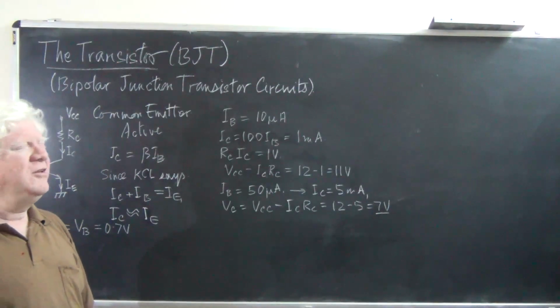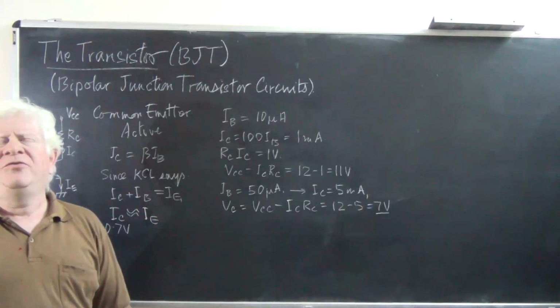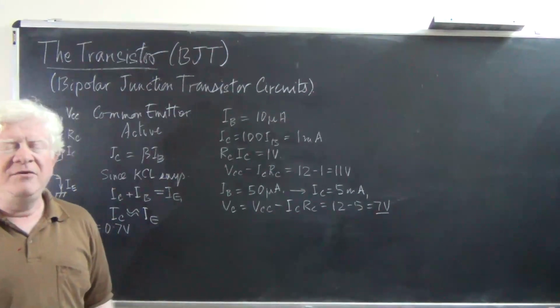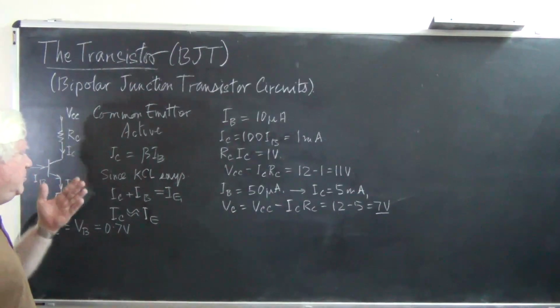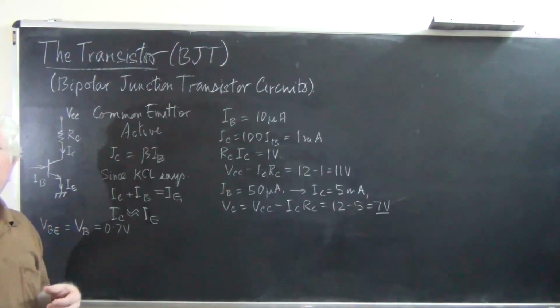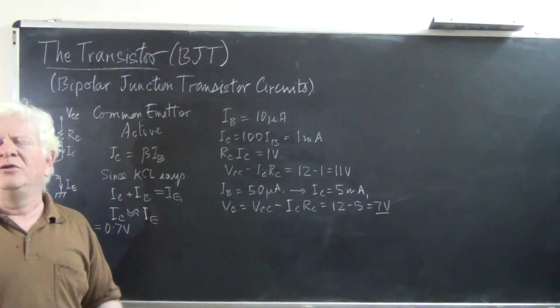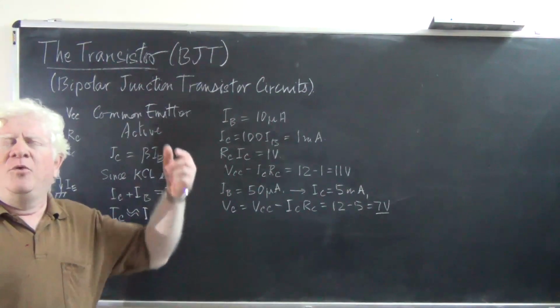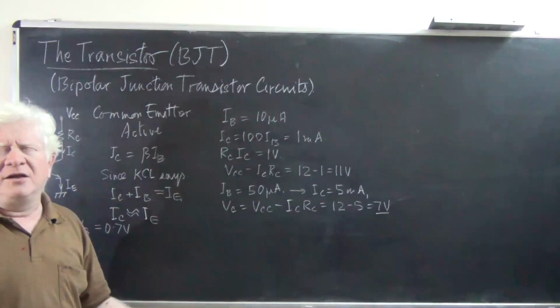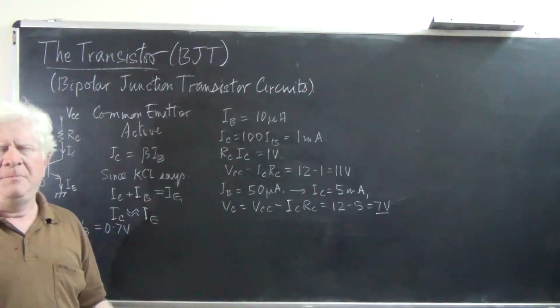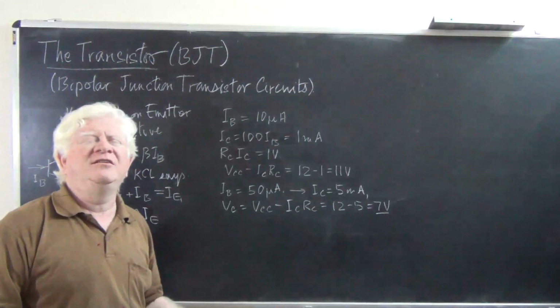Our first experiment consists of examining the behavior of this network at its extremes. What we will do is to pump in so much base current that the collector current is so large that the voltage of the collector comes down to practically zero. Practically zero is the term because it doesn't exactly come to zero.